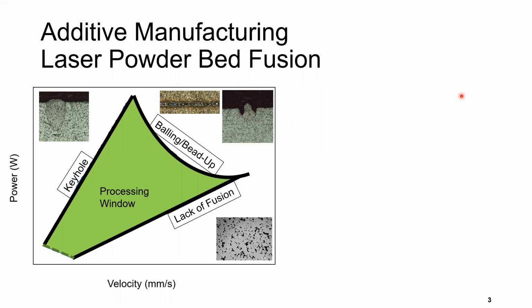At a low laser power and a high laser velocity, you have a difficult time making sure that your melt tracks overlap properly, causing fusion errors. And this manifests as very jagged shaped pores in your three-dimensional part. So this is also not desirable. You might think that at high laser powers and high laser velocities you lessen the severity of these types of problems. And to some extent, you'd be right. However, this is where you start to see the Balling phenomenon occur.